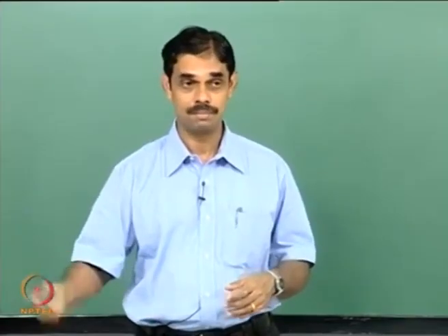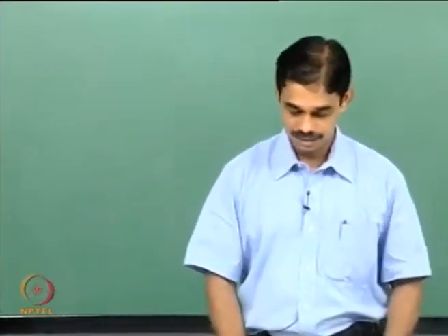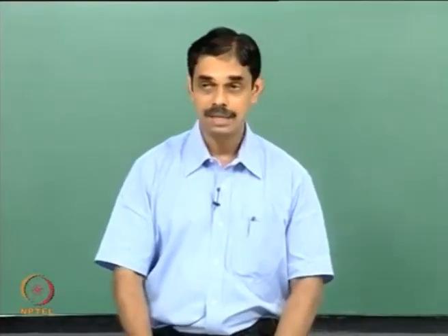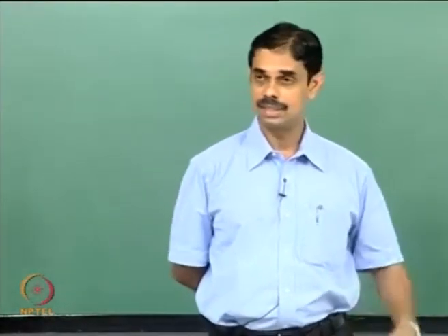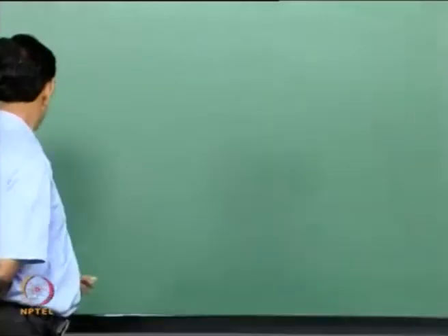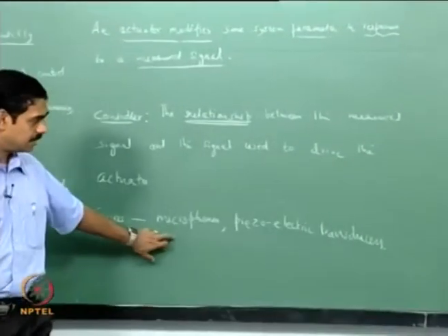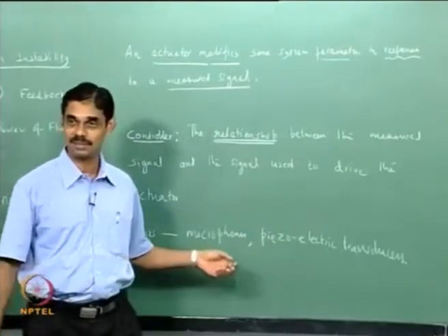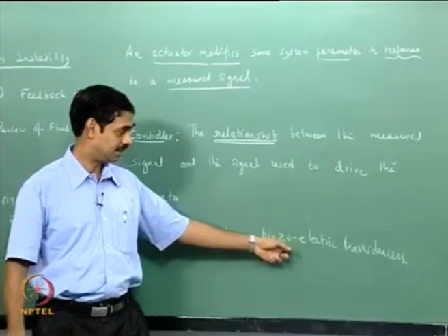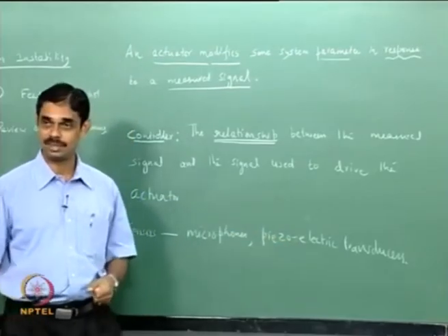So there is an option to keep them away and you can still measure, and typically microphones have large bandwidth and they are reasonably robust. Microphones may break at large amplitude, and if you drop a microphone it will surely get spoiled. Piezoelectric transducers are much more robust.